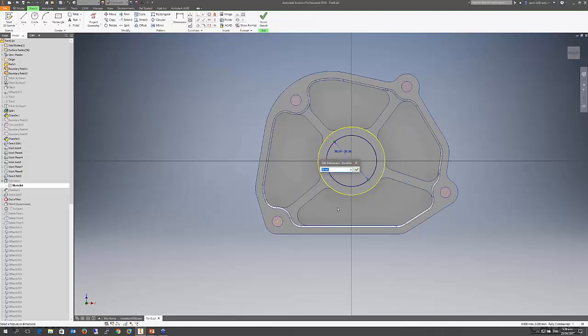That was originally placed as a dimension on the sketch, and then I typed in the nominal diameter of 30 millimeters. There are a number of advanced users in our customer base that still haven't used the tolerance feature on that dimension, because a lot of designers just work on nominal. They model everything nominal, and then in the 2D drawings, they put tolerance notes on dimensions. But the thing we're getting at today is that you can actually tolerance the model.